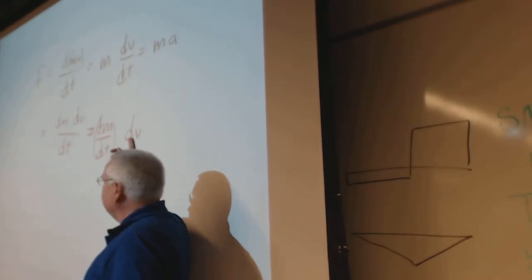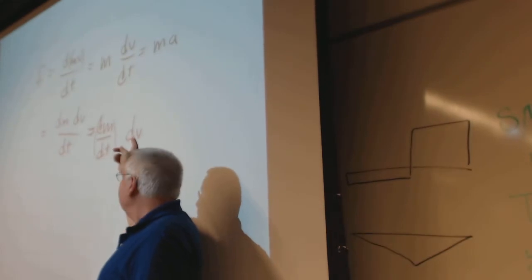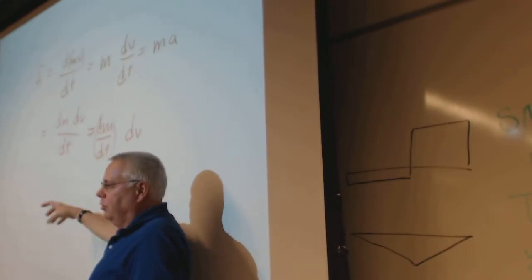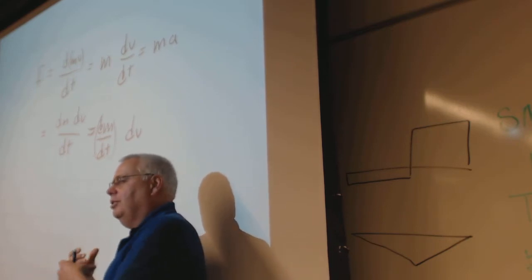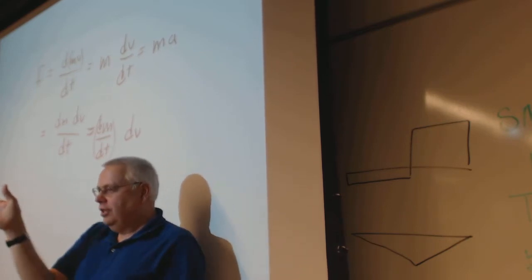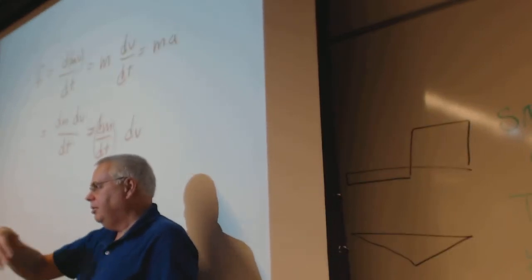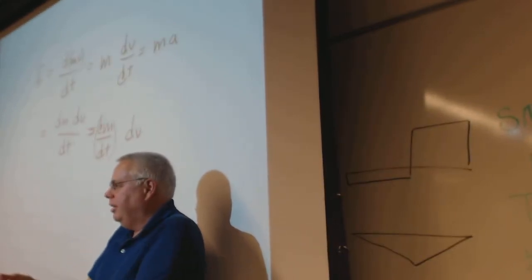There's a change in velocity right at the nozzle at whatever mass flow rate. The hose is delivering the mass flow rate with some pressure, and you turn that potential energy into kinetic, and the end of the hose starts whipping around because you're not guiding it anywhere.